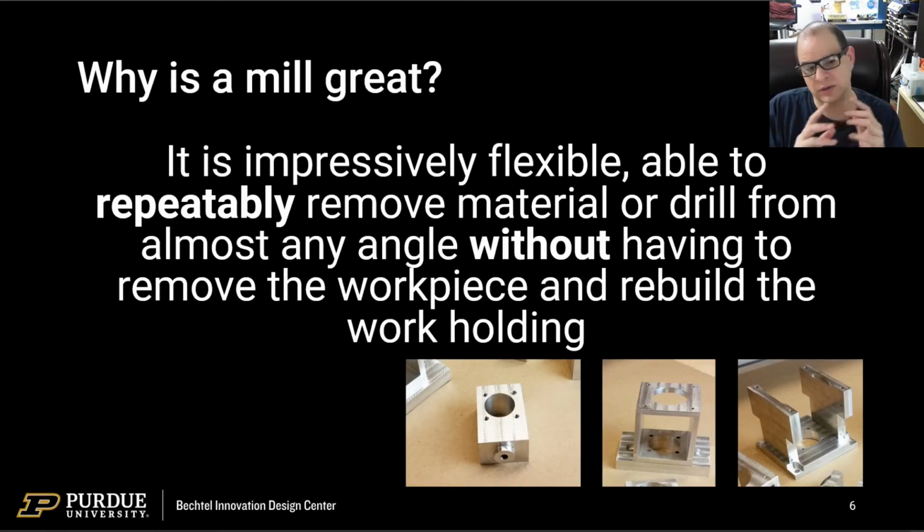One thing to note about the paths, and we'll talk a lot more about this in mill operations, is you can see you've got sharp outer corners, but if you look at the inner corners of a part, you can see that they're rounded or the holes are circular, and that comes from the spinning cutter. It's very hard to impose a 90-degree turn on the corner on the inside of a cutting piece when you have a round cutter, round like my finger is round, going round here. You can't make a 90-degree corner here. On the other hand, on the outside of the piece, you absolutely can use a round cutter to cut a very sharp right angle just by moving it correctly.